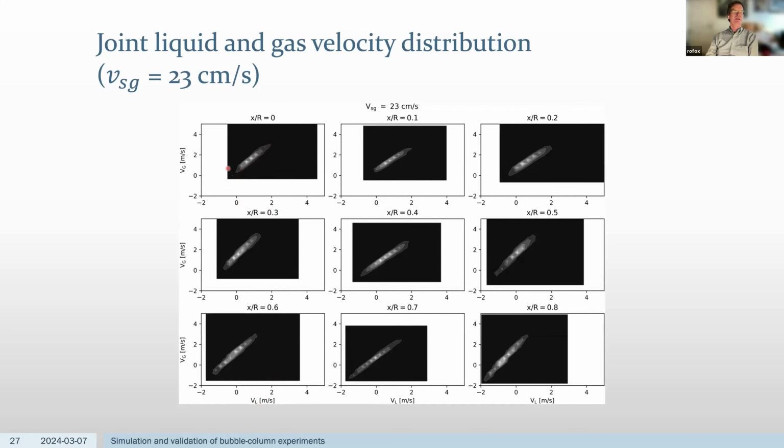So basically we get linear plots between the two. There's a linear growth, so a linear correlation between the two velocities. And 0, 0 is, if you go up from there, you get the slip velocity for the gas bubble. So in each case, you can see 0, 0 is slightly higher. So if you know the slip velocity, then there's a linear correlation between the two velocities. There's this offset in each case by the slip velocity at that location.